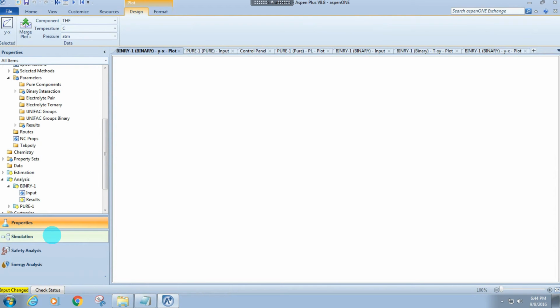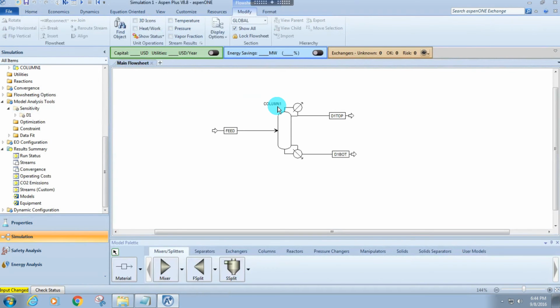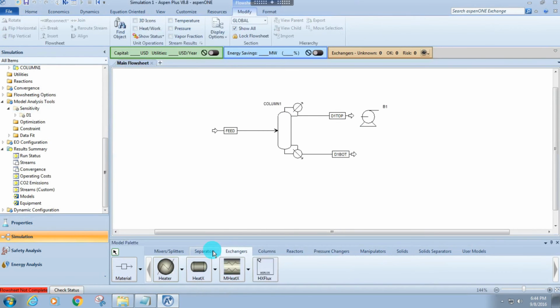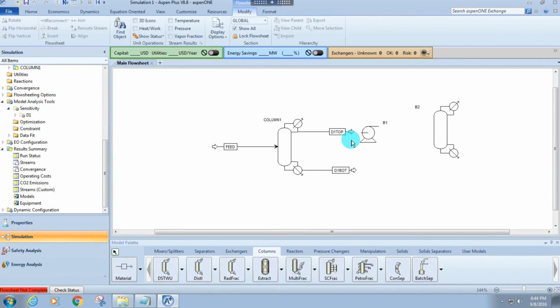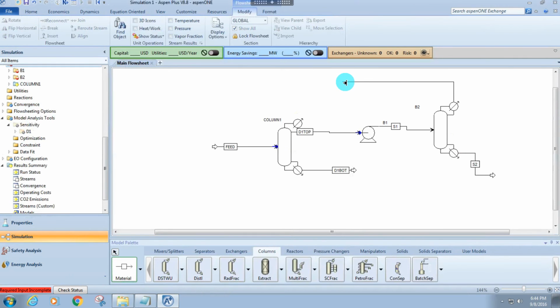Okay. So let's replicate what I have on the board. We want to increase the distillate pressure to 15 atmospheres and feed it to a second column. Just a quick comment, if you chose to do the vapor distillate, then you would need a compressor instead of the pump. So if you know you're gonna do PSD, it's kinda better to just do a liquid distillate, so then it's really easy on the pump to get it into the second column.